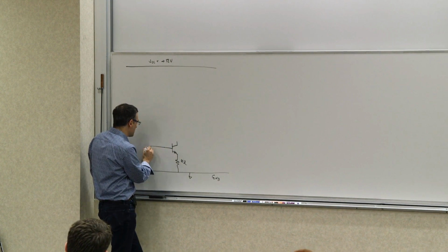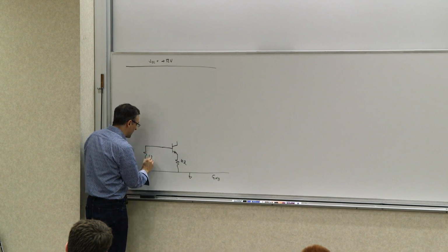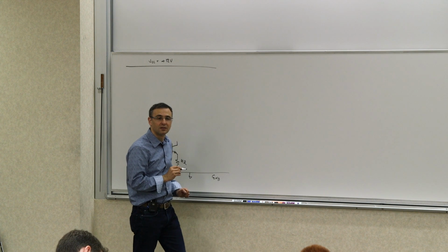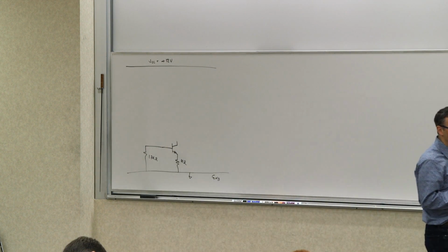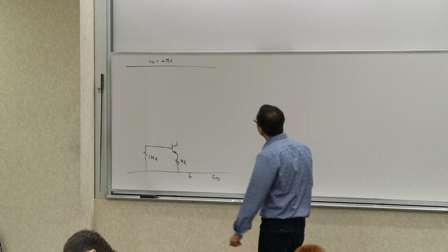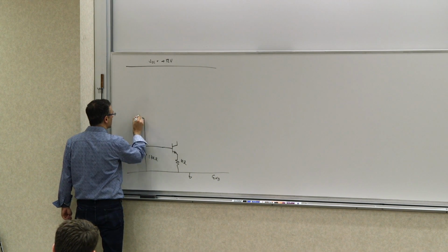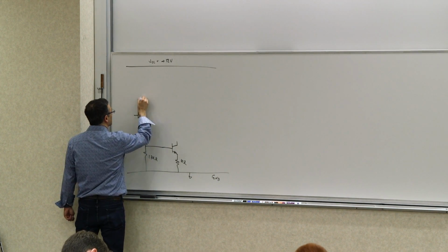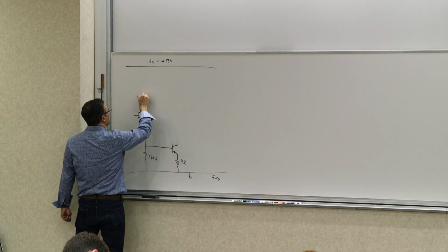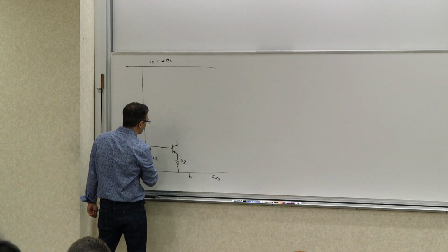So let's say I use a branch, so I make this 1.7. So let's say I have another branch with 1 milliamp, so I make this 1.7 kilo ohm, right? And if I pass 1 milliamp through that branch, then it should provide me with the value that I need. So this 1.7 kilo ohm can also serve as that current source that I have for the follower. So I can put my follower here and use this as the driving force for that. So this is 1 kilo ohm, 1.7 kilo ohm.